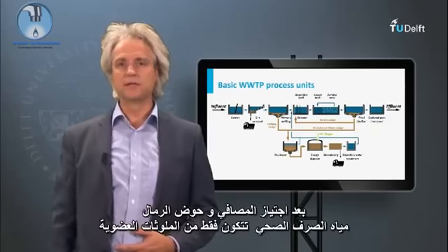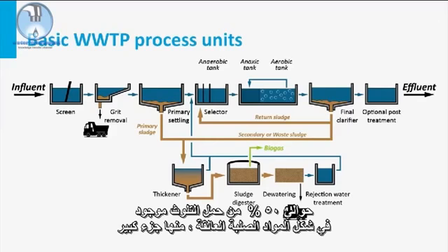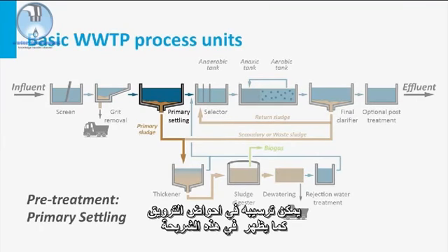After passing the screens and grit chamber, the sewage merely consists of organic pollutants. About 50% of the pollution load is present as suspended solids, of which a large part is settleable in a clarification tank as indicated in this slide.